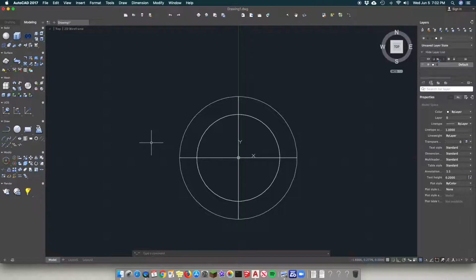Alright, so we've created a sphere. Now we need some lines that we're going to turn into planes, like surfaces, that are going to be used to slice this object. We haven't done slice before, this is new. Basically if you have a 3D object and a plane that intersects it, think of it like a knife cutting a potato, you can then say I want to get rid of parts of this. So it's very important that we do these dimensions.